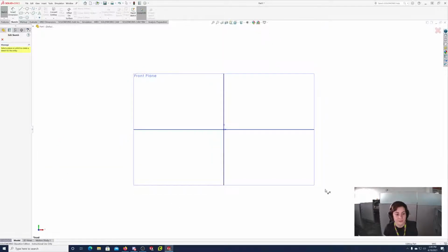And you can see our background color changed a little bit. And then to see the origin, so we have an origin, we can kind of see it right here, but we're going to click the View drop-down menu and select Origins. So that's up here at the very top. Next to File, Edit, and then View. And you're going to go down to Origins.